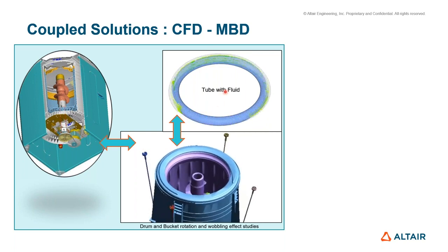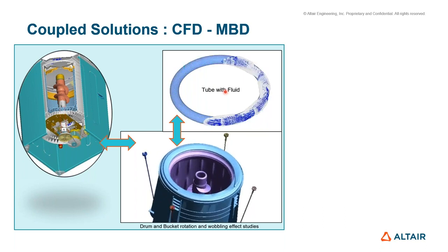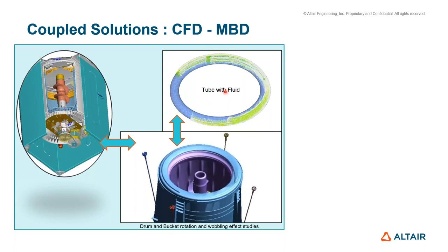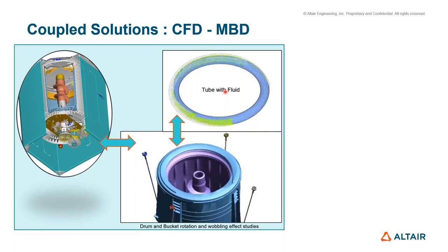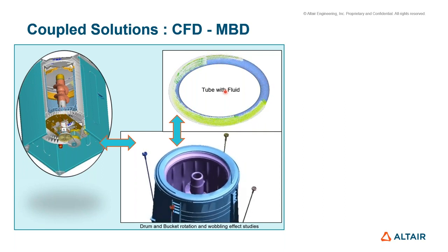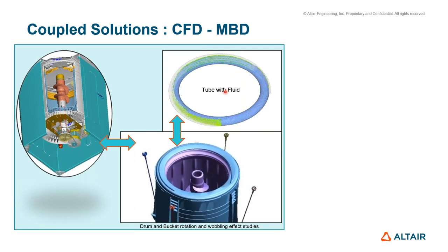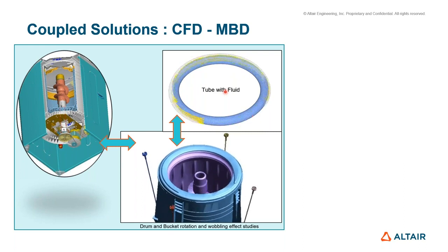This balancing is very interesting, where you have a fluid-filled ring at the top of the tub. As the load shifts in the washer, the load may become more concentrated on one side of the basket, and fluid in the balance ring shifts to the opposite side. Beautifully engineered, it offsets the weight and keeps the rotation of the basket stable. That's the overall use case we would like to solve.